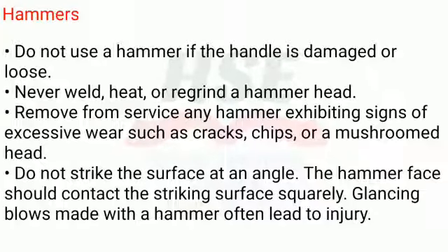Hammers. Do not use a hammer if the handle is damaged or loose. Never weld, heat, or grind a hammer head. Remove from service any hammer exhibiting signs of excessive wear such as cracks, chips, or a mushroomed head. Do not strike the surface at an angle. The hammer face should contact the striking surface squarely. Glancing blows made with a hammer often lead to injury.